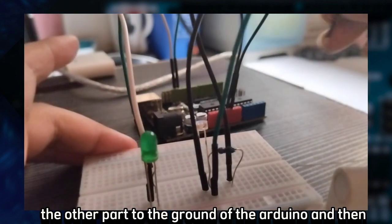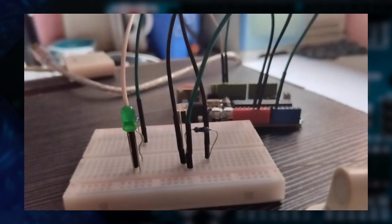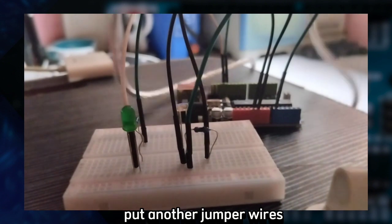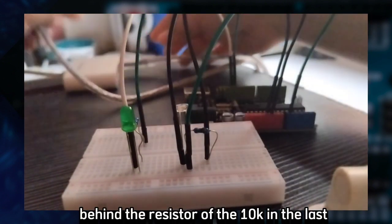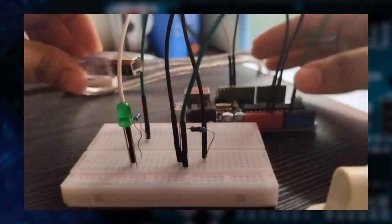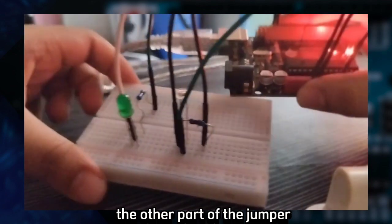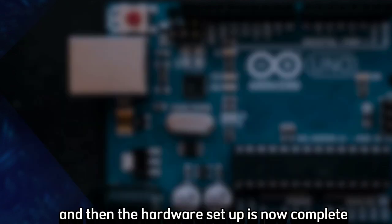and then connect it to the ground of the Arduino. Then put another jumper wire behind the 10K resistor in the plus, and connect the other end of the jumper wire to the serial. And then the hardware setup is now complete.